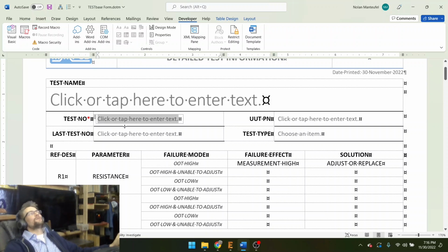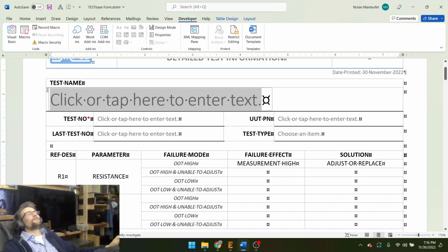So test 1, right? The bus, the V plus rail short circuit test, where you put the multimeter across plus and minus, and you see if it's short circuited.